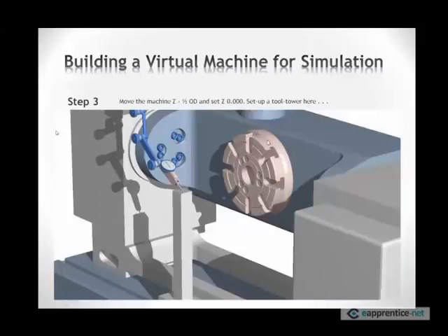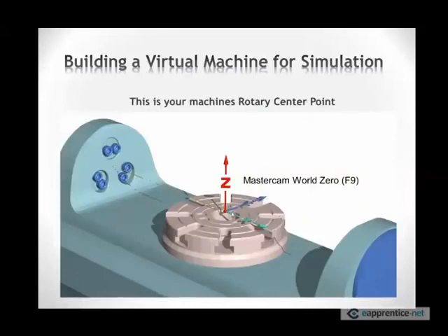Next step is to measure that OD and move half the OD, the radius, down and build a tooling tower that sets our indicator back to 0. So we move the radius; it was reading 0 up here, with the radius reading 0 here, meaning that we are in the center of this OD. Now that point on most machines won't fall perfectly on the table. On some machines it will be below the table, on some machines above the table. On this rotary device I measured, it was 0.1403.